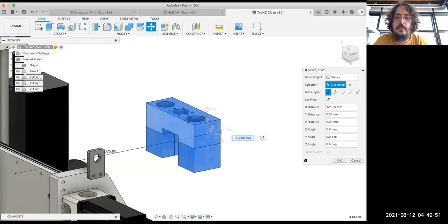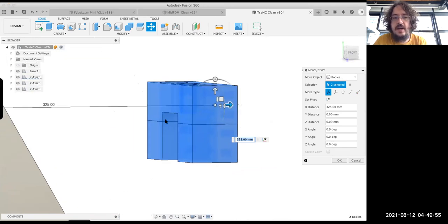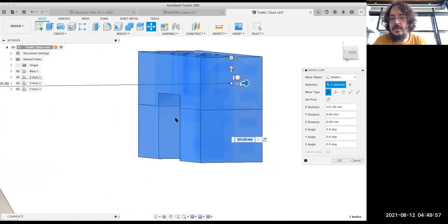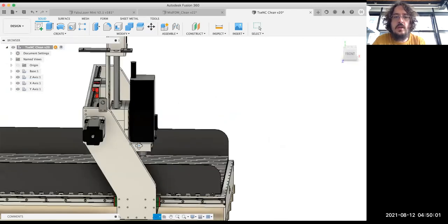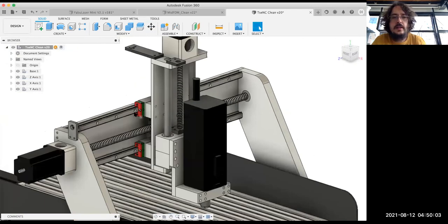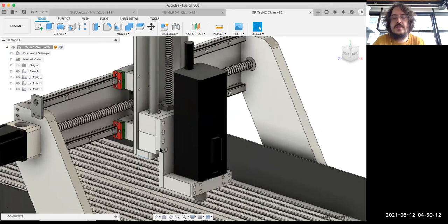And these pieces are complex to manufacture. I was manufacturing them by having a very long end mill, for example, to manufacture these slots, and this was very long. So in the future, I would advise you to also use rails here on this plate to avoid having these 1, 2, 3, and 4 pieces to produce. So they will be much faster.